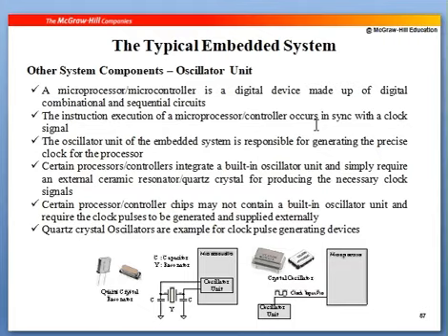But we had already discussed that the main application of your Cortex machine is for those applications where the power is lesser and the performance is greater. But there is always a trade-off. If you want very good performance, then the clock frequency should be higher, but it will also create a problem. The power required will also be higher.